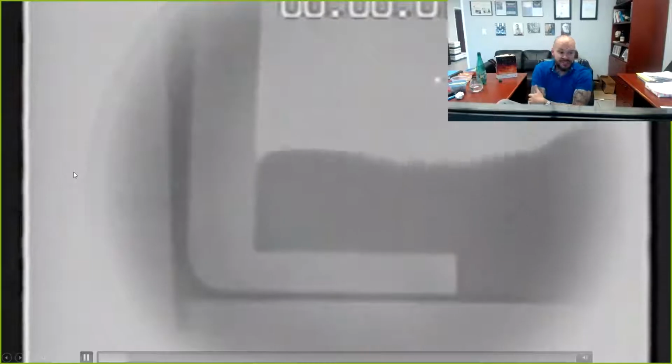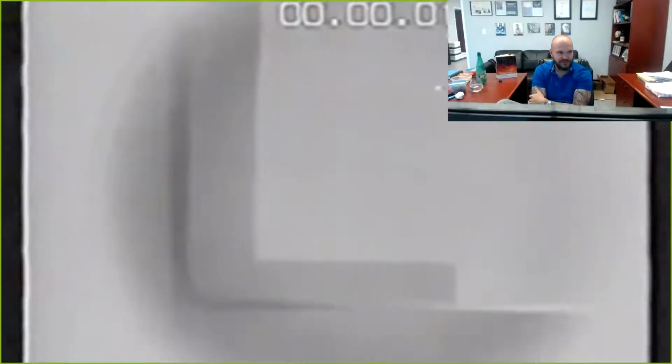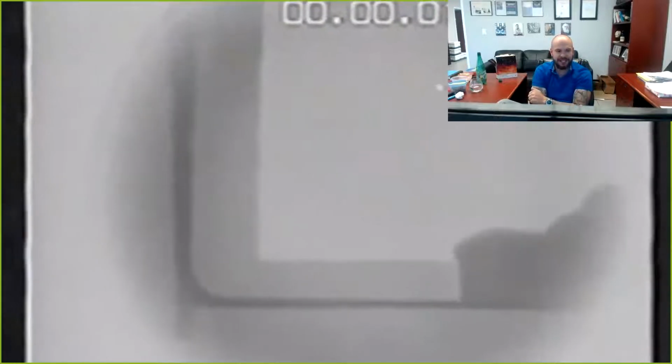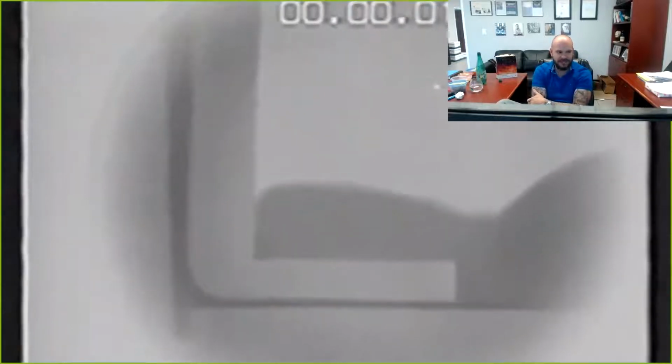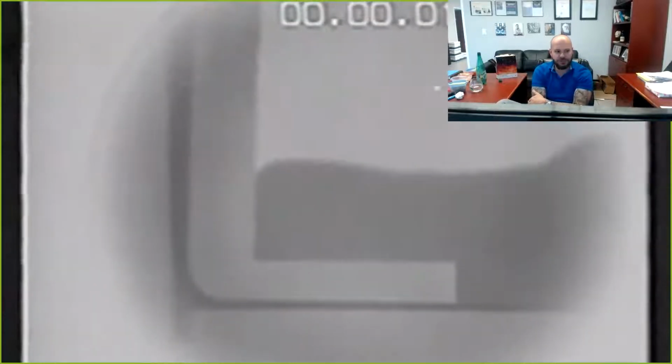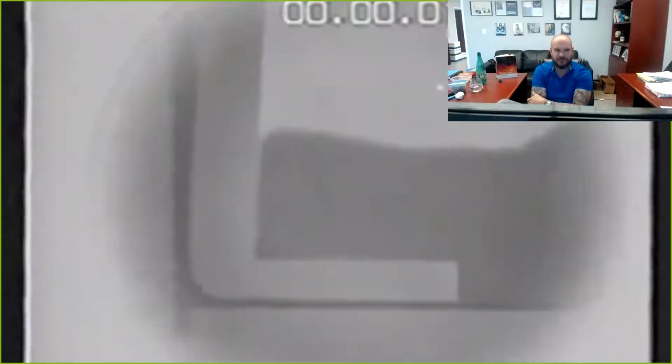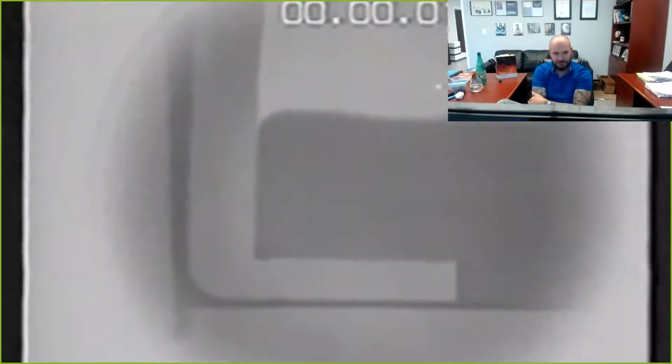So this was the first attempt at designing by volumetric constraint, or what is now known as the naturally pressurized filling system. And you will notice within the running system and within the casting cavity that we have no air bubbles, right? Now you can see that there's a ton of turbulence as the metal's entering the casting cavity, and we'll get to that later. But what we know now is we can drop metal vertically, transfer it horizontally, without the entrainment of air bubbles or without the entrainment of bulk surface turbulence, which rolls that oxide film into the bulk.